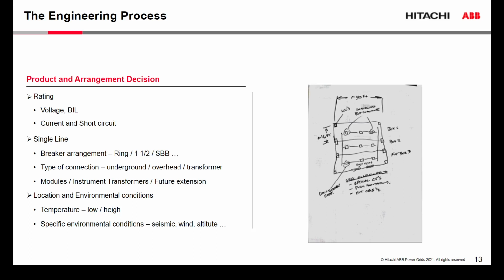And last but not least, if it is possible to know the temperature. North America is pretty large and the US itself is very big, so you can have temperature requirements in Arizona where we have already in the mid-90s up to, I believe, 55 degrees C in the specification, while you go further north and you see easily -40, -50 degrees C in the specification, which could have impact on the design of a substation.